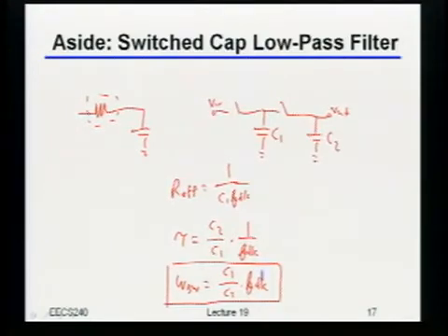So if this was precise and well known, you should be able to do a darn good job with setting that. And now, of course, if you wanted to tune the thing, you could just tune either C1 or C2 and actually shift that thing. And as long as you knew what the ratio of the tuning you were doing was, you'd know very precisely where is the low-pass filter corner that you've set.